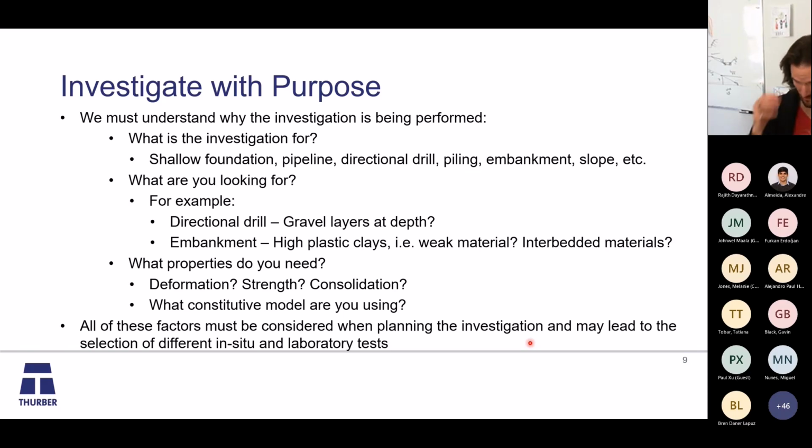If I have a directional drill, maybe I'm concerned about gravel layers at depth. Or for an embankment, I'm concerned about high plastic clays, interbedded materials, weak materials. So you've written a proposal that says I'm going to take this many Shelby tubes, or these many samples. But in the field, you should have this context of, okay, what matters? And then you can adjust that program so that you're actually collecting the right things.